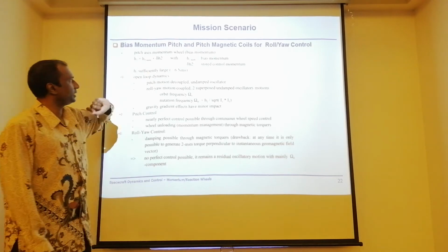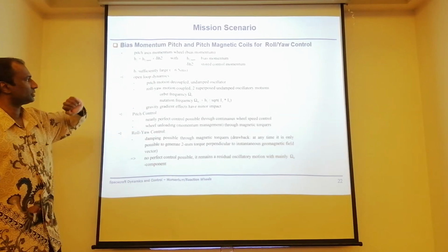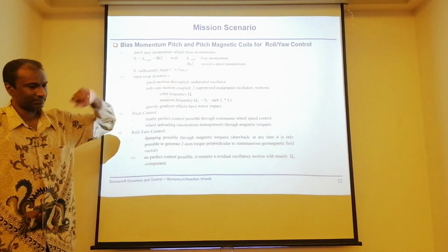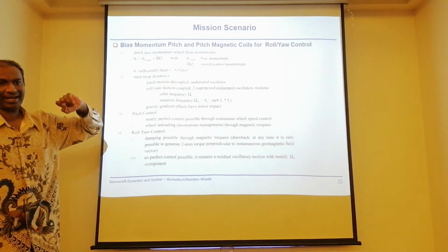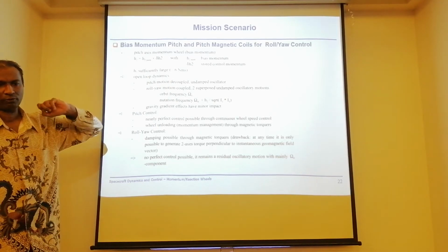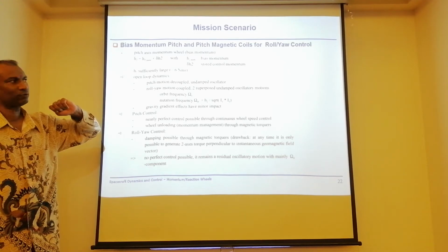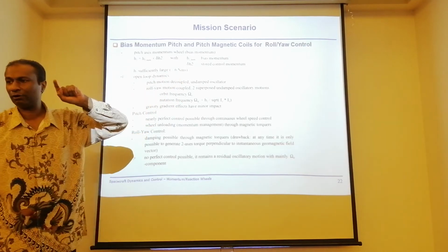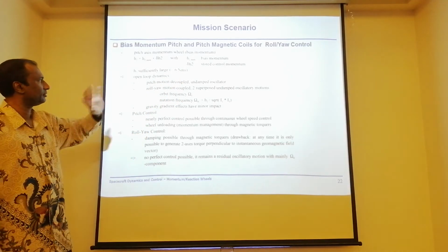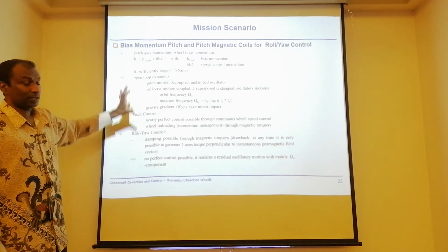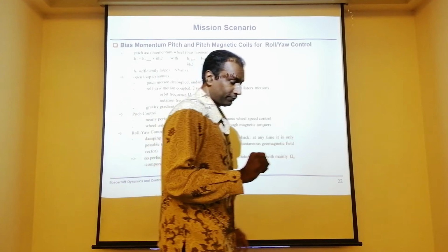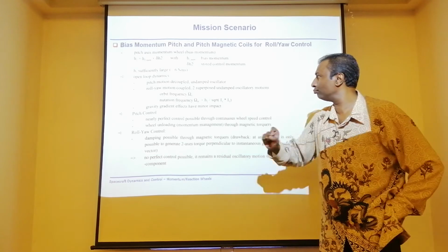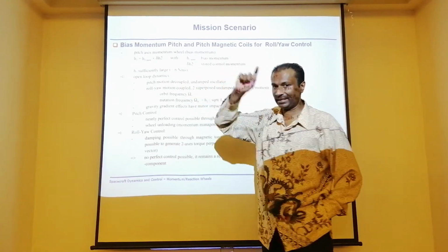So I have basically the bias momentum stored there, highly sufficient, about 6 newton meter second. In some exercises that you saw in the last chapter, chapter 5, where you have all those magnetic torques, you have also seen an example of 8 newton meter second of bias momentum. Yeah, you have that. It's an open loop dynamic. Remember the B-dot pointing? That is an open loop.